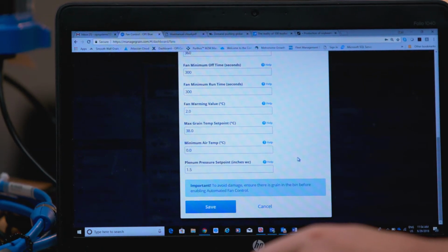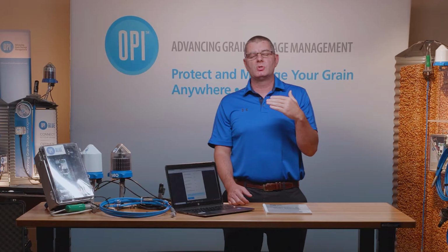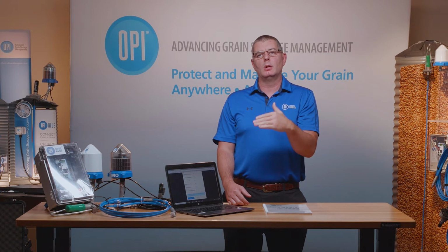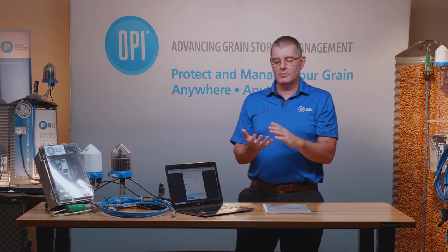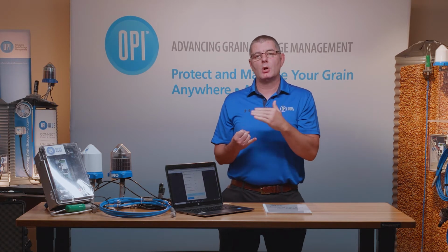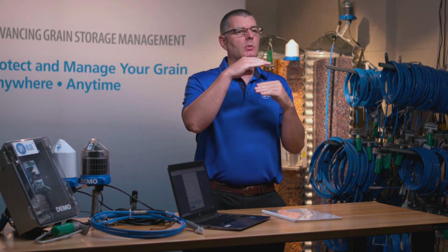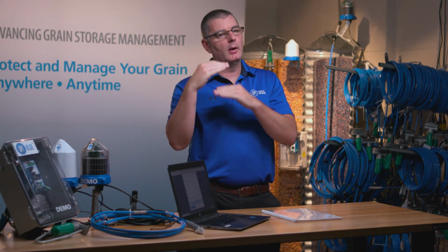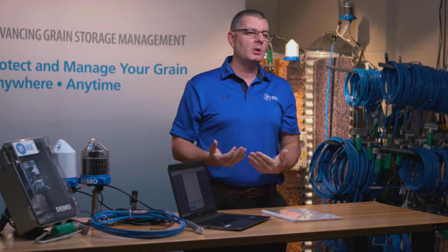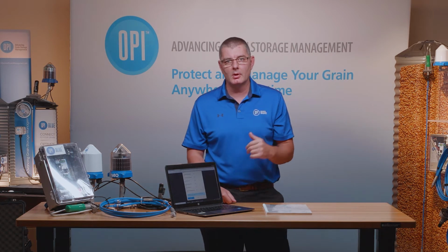Minimum air temperature and plenum pressure set point. Minimum air temperature is just the minimum temperature you will allow your fans to run at. It serves two purposes. It makes sure that if you don't have grain in the bins, the fans aren't going to run without grain being in the bins, because it's able to recognize temperatures of sensors on the cables within the bin, and when there's no grain in the bins, no sensors in the grain, it's not going to allow the fans to just kick on, which can cause damage to the bin itself or the aeration floor.